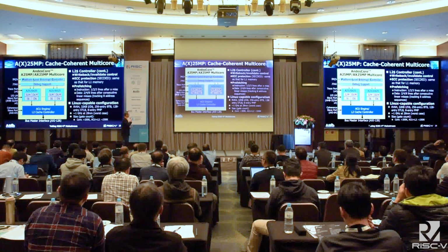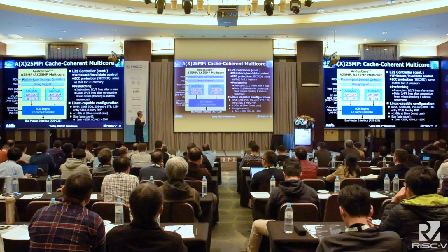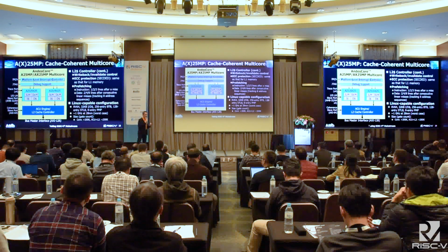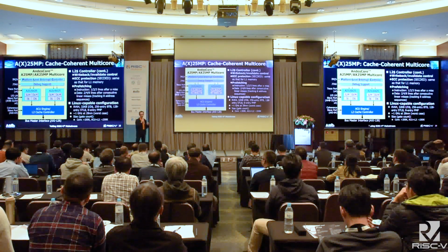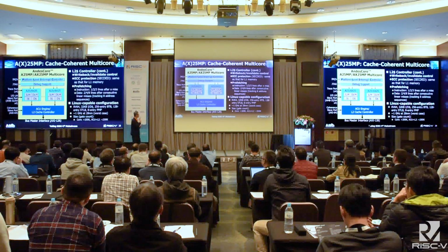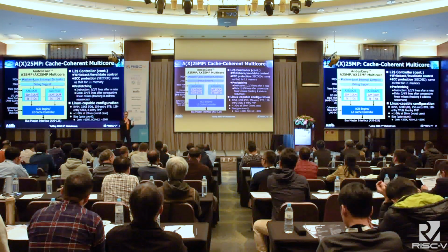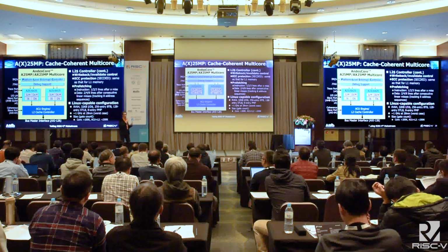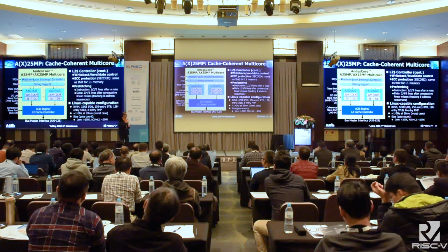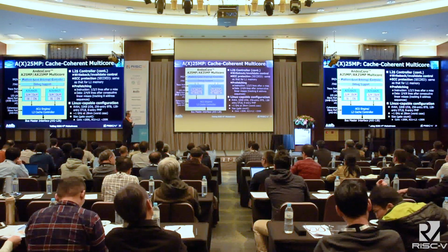And for the data, it can continue to watch 8 different address sequences, and then based on, again, selected misses, it will start to do a prefetch. So either 2, 4, or 8 lines.